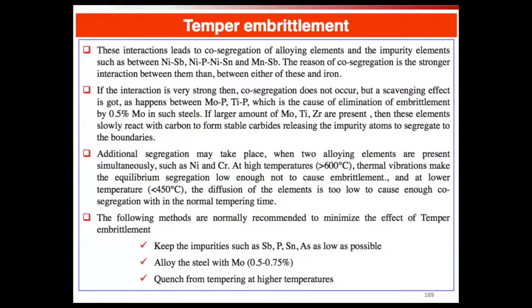What does it mean that something reduces the energy of the grain boundary, reduces the cohesion? It just means you have to put less energy in to split it. It's the same as a continuous film of cementite.